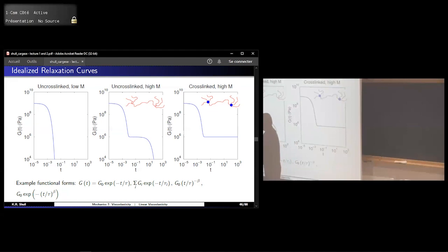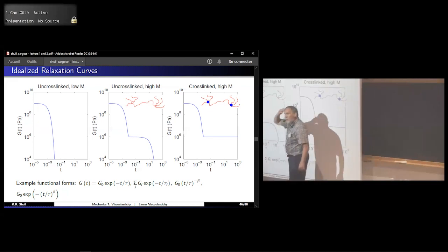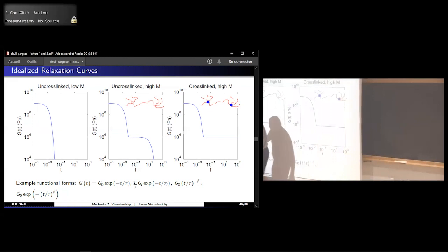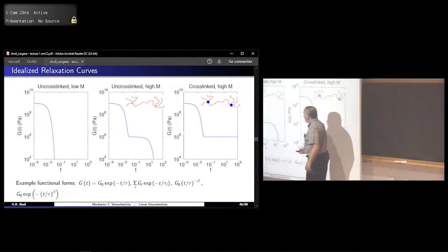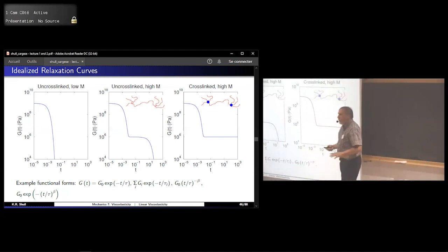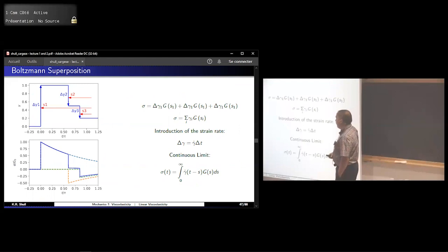In my experience, rheologists get a little bit grumpy when you do things like this. They like the single exponentials. Even Ralph Colby had to apologize when he was using that form. But it's still a useful way of sometimes representing your data if you just want the curve to go through the data, and sometimes that's what you need. So that's what the relaxation modulus is.